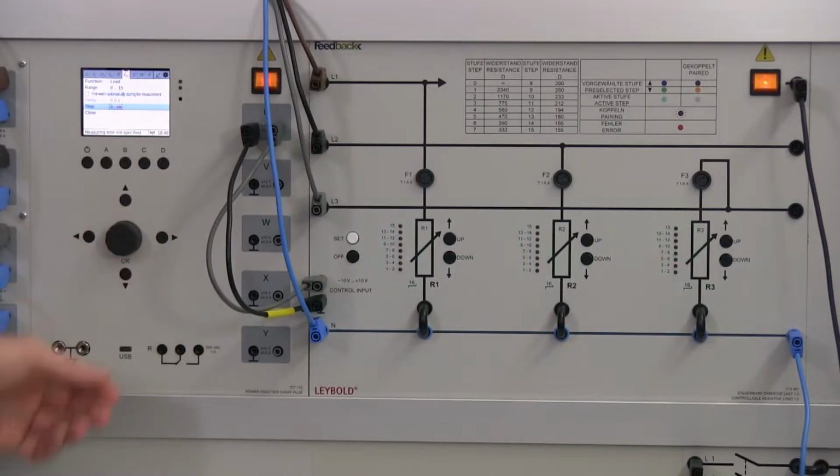The main benefit of this remote control mode is, of course, that we are able to connect to the Power Analyser CASSY Plus with our LabDocs or with our measurement software CASSY Lab 2, and then control the load via these two instruments. So students can directly control the load within the instruction sheets, and are able to vary the power consumption in their setup.